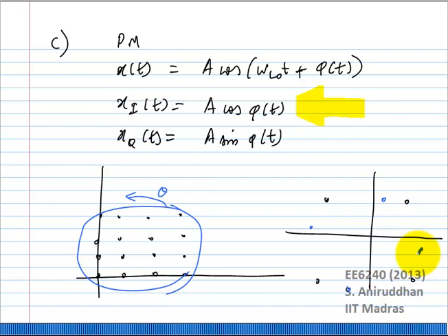You usually transmit a pilot symbol, which you already know, and based on the phase of the received pilot symbol, you then shift the phase of everything else that you receive after that. Is that clear? So that is the easiest way of taking care of this kind of phase shift, because this is actually a fixed phase shift.